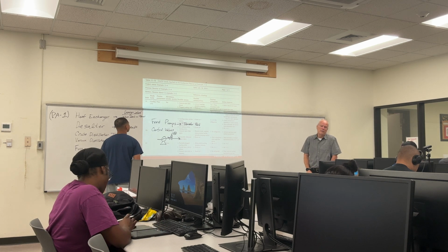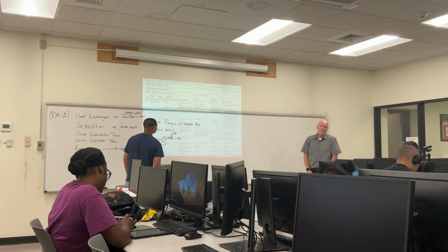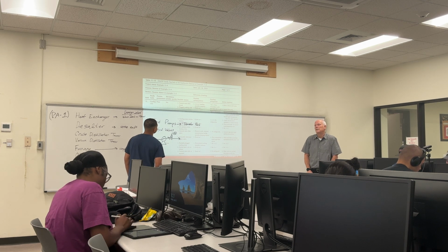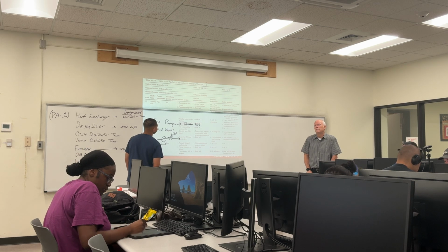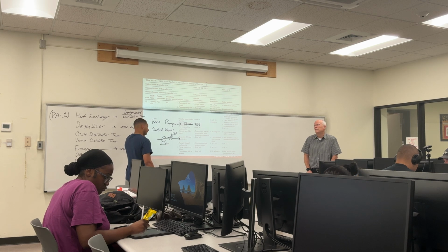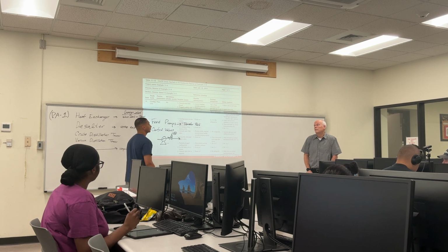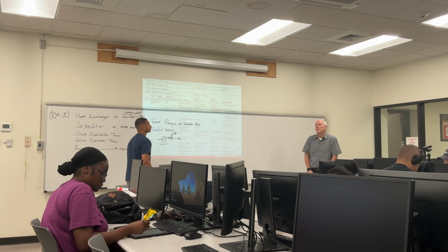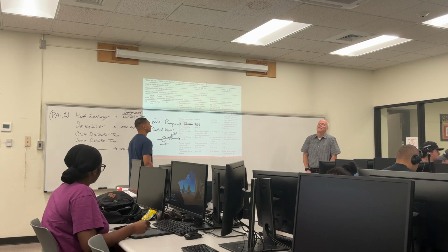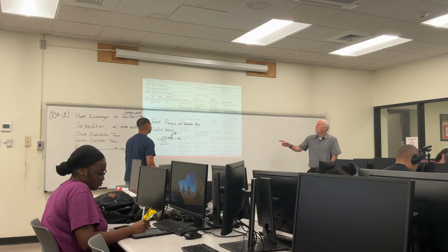And then, what is an existing safeguard so that that does not happen? Probably gonna be a control valve on the furnace. Excuse me, is it a relief valve? Relief valve's not gonna help you. What did you say? Control valve on the furnace, you can set up a low flow alarm. A low flow alarm's not gonna really help you unless you know that it's happened.